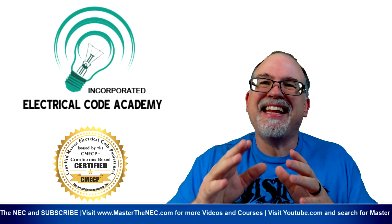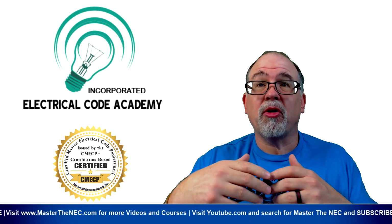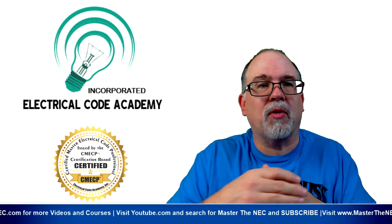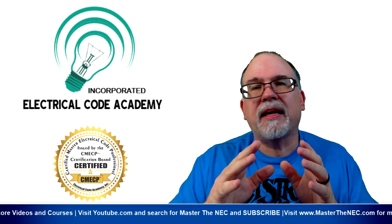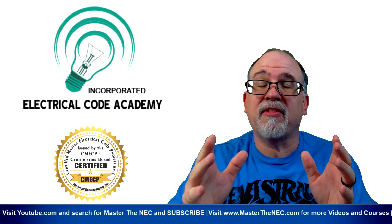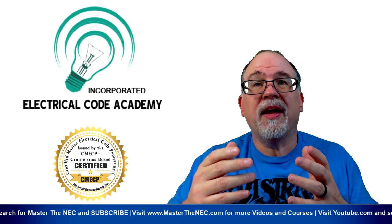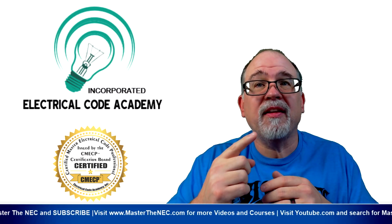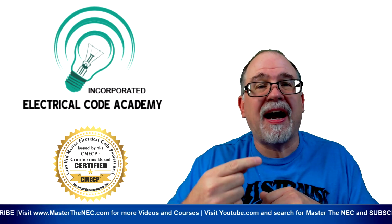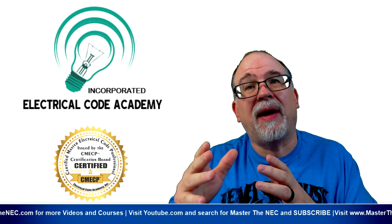Now, we're not going to get into power loss applications, because generally you can also utilize primary protection only, without overload protection, if you're dealing with things like fire pumps or critical systems. Just remember: primary protection and secondary protection in all cases in transformers, except when we're dealing with a single-phase transformer with a 2-wire secondary that has one voltage value, or a delta to delta 3-phase where the secondary is a 3-wire delta with one voltage value. Then the primary can protect the secondary windings in that case.